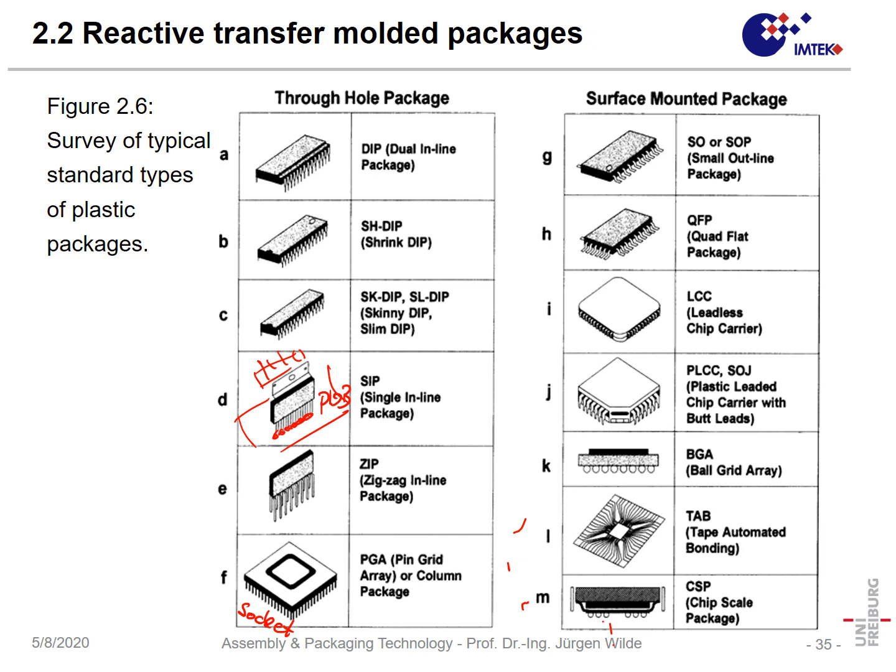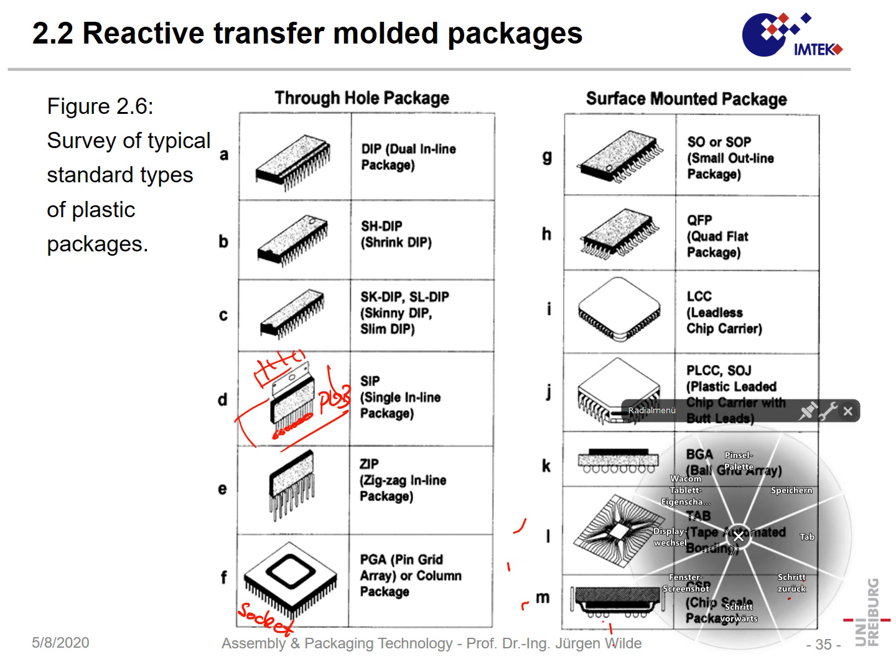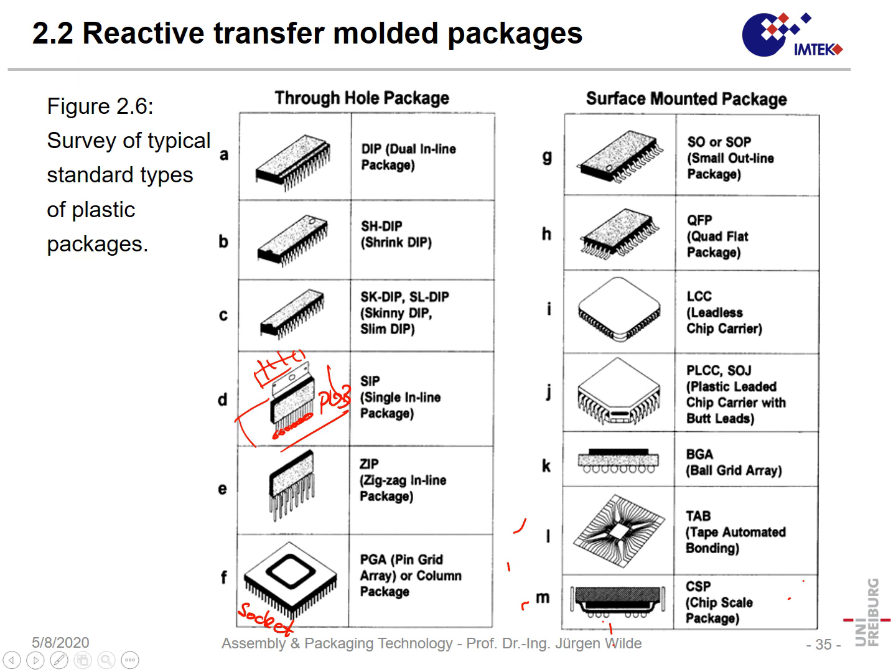making the device smaller and bending the IOs like the legs of a dachshund gives us a surface-mounted device. Then the next step was new, putting these IOs on all sides of the device. You can bend them outwards, you can bend them inwards, then it's a leadless chip carrier, you could say it's out of date. And then we have PLCC, which is again a similar package.